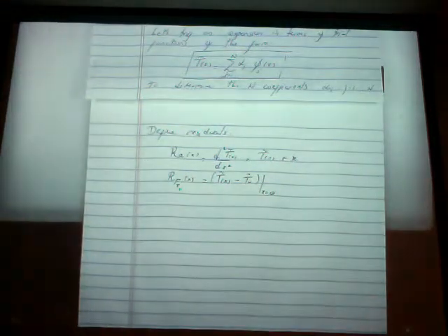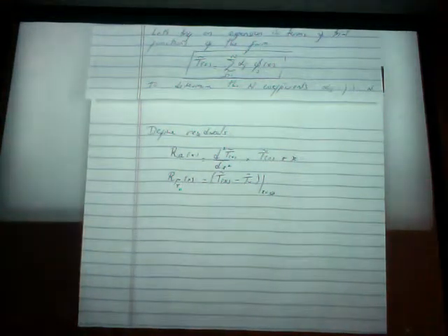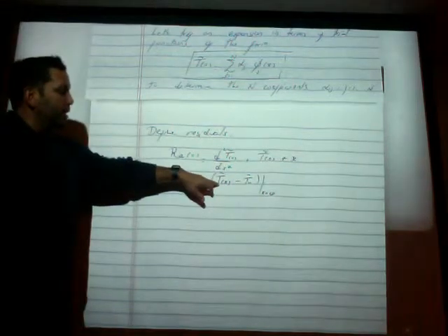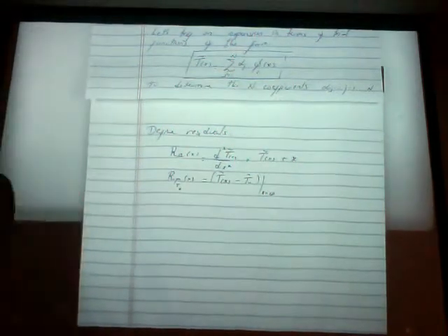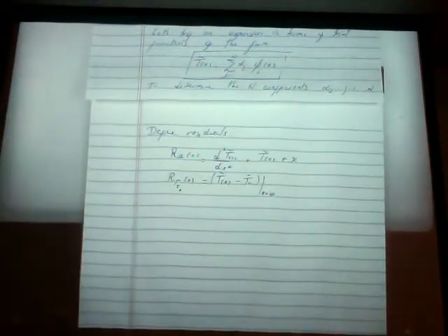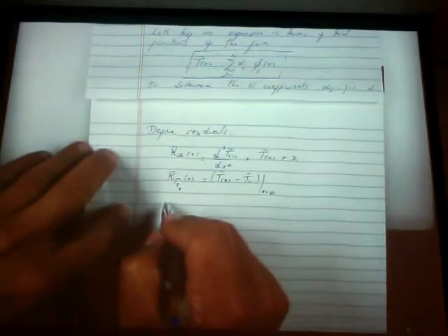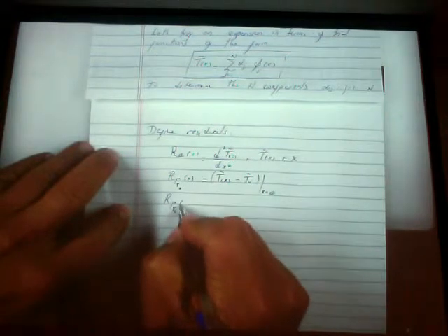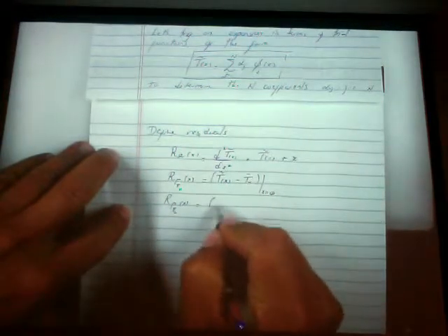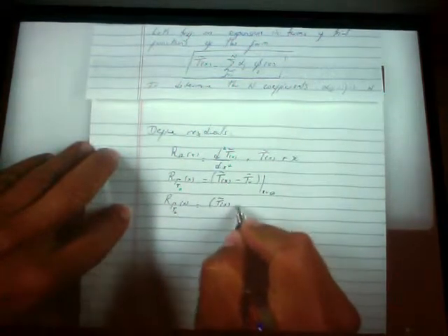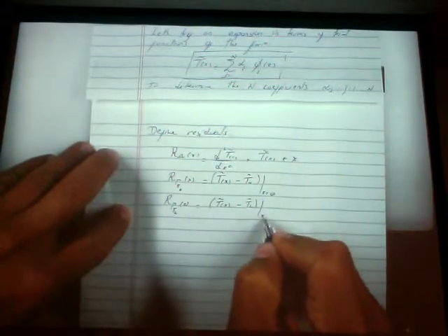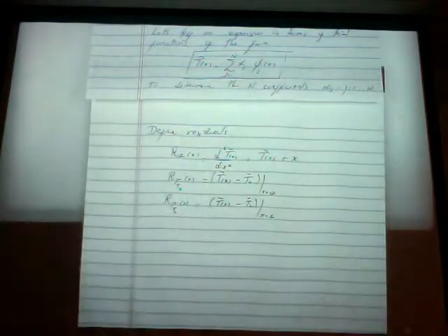Okay, there's no integral, since it's a Dirichlet condition, it's just the defect between the approximate solution and the imposed boundary condition. And then we have another portion of the residual on the portion of the boundary at x equal L. And that would be this approximate solution minus the temperature that is imposed at x equal L.